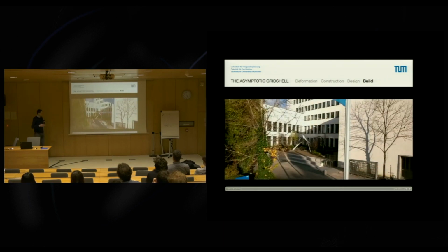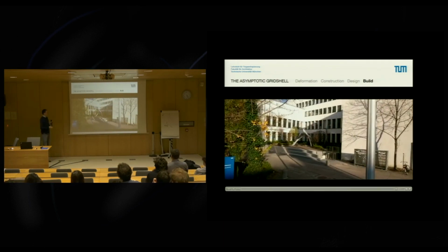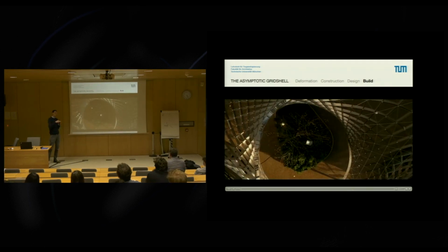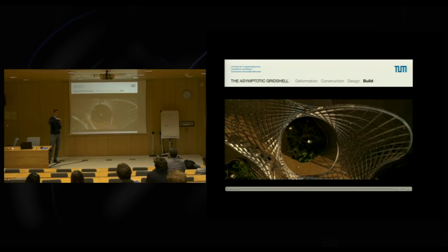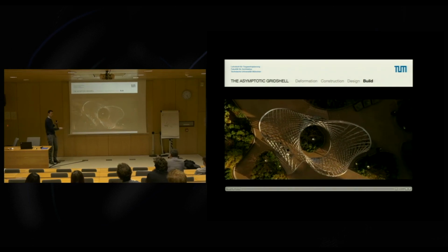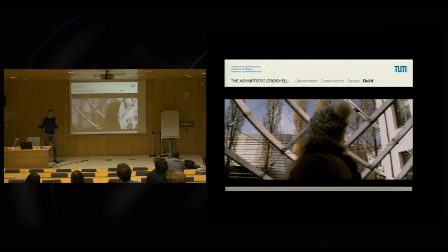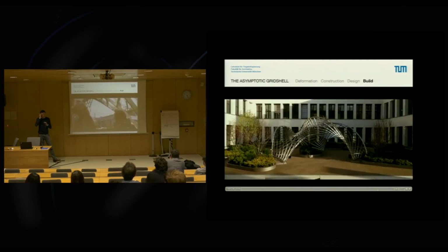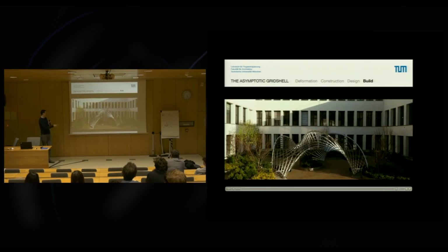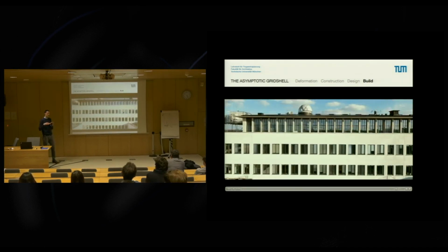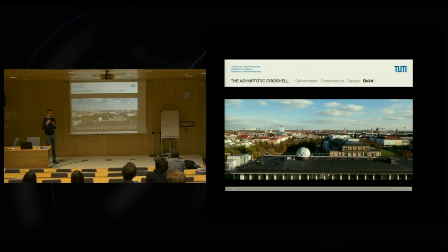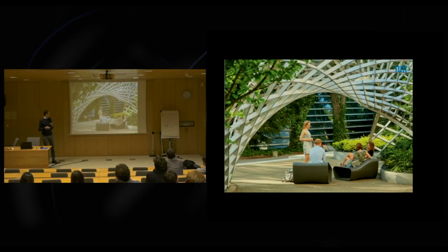So the whole grid shell has a high curvature, and it was a real challenge to find a minimal surface that would also have the characteristics of a funicular form. So we really tried to have these arches so that it would nicely carry the loads down into the supports. Finally, what I want to say is such a grid can be easily paneled as well. We have paneling solutions, because it is exactly bisecting the principal curvature lines. That means if you put panels at a 45-degree angle, you can put planar square panels of glass on this structure.